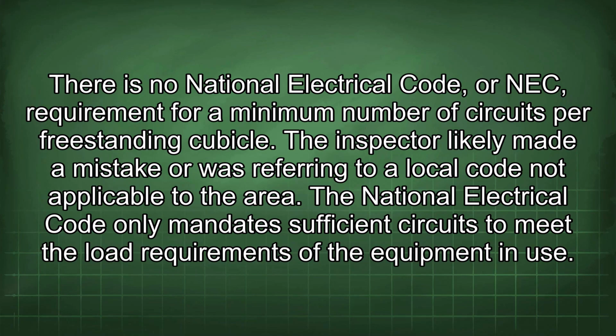There is no National Electrical Code, or NEC, requirement for a minimum number of circuits per freestanding cubicle. The inspector likely made a mistake or was referring to a local code not applicable to the area. The National Electrical Code only mandates sufficient circuits to meet the load requirements of the equipment in use.